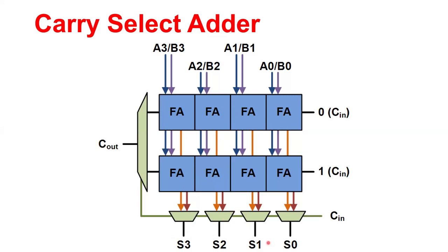That means the sum lines receive the orange outputs. So there is no question of carry propagation at these stages, because no carry is generated. So the conclusion here is that this architecture is relatively faster compared to the standard carry ripple adder, where the carry ripples through all the stages.